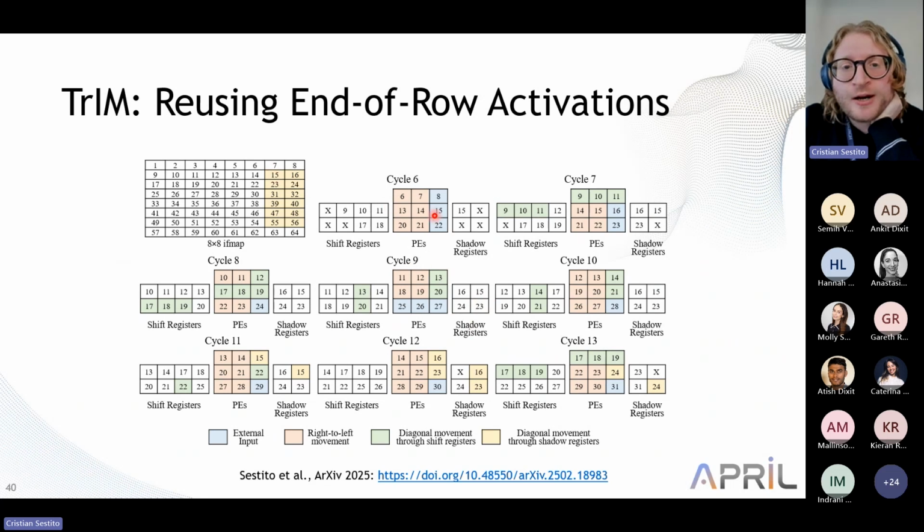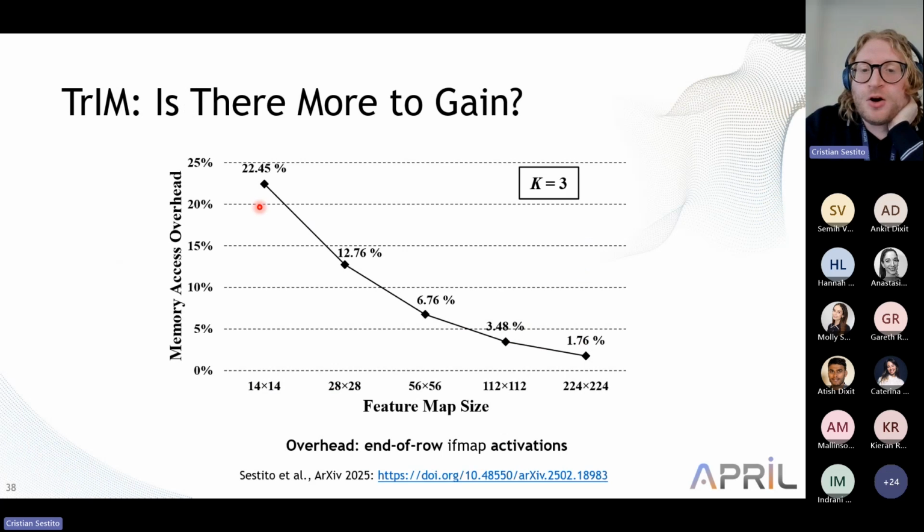As an example, here we are referring to the process between activations 6, 7, 8 through activations 29, 30, and 31. And basically, as you may see, as we move through the clock cycles, the border activations are stored at that level. Once we store the target activation that needs to be reused at some point, we freeze those registers, so we don't allow any further readings, and we keep the data until it needs to be used. In particular, we highlight in yellow this type of data reuse. With this approach, we are able to completely get rid of this problem.